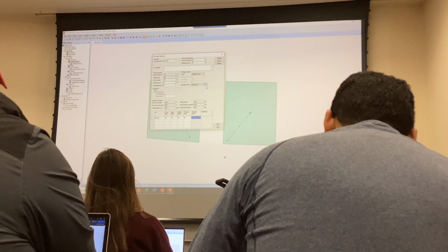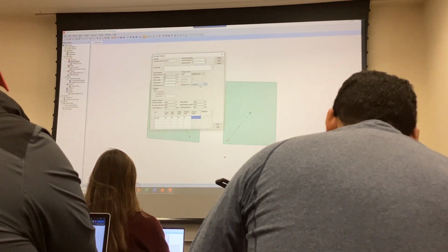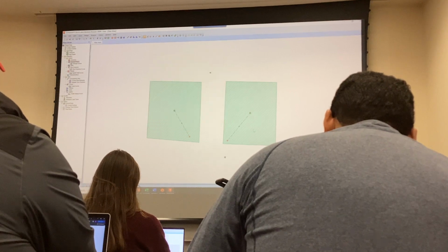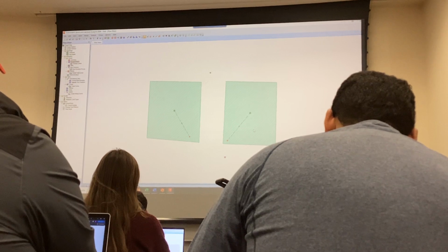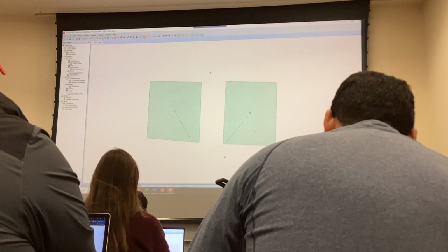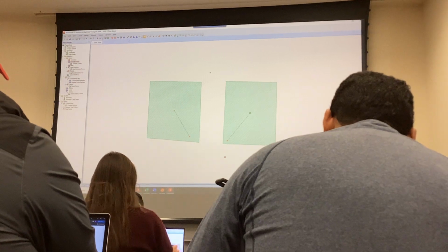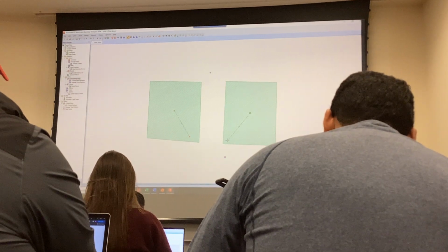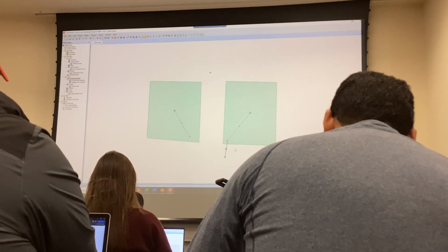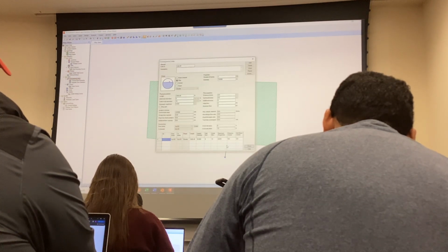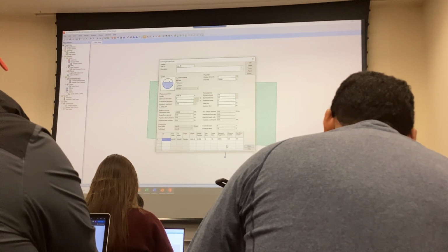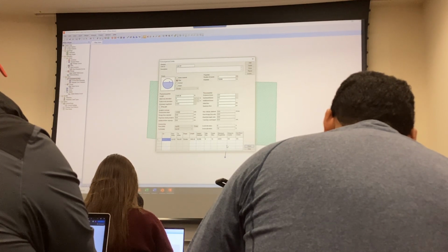And now you have Storage 1 over here, and that is going to be the name for your detention basin. The name is Storage 1 for your detention basin. Okay. So the question becomes, how do I actually pipe things into my detention basin, right? Now, this is when you need to create a connection, a link. There are many types of connection. You can have a pipe system to go into your detention. You can have open channel flow that goes into your detention, or whatever.